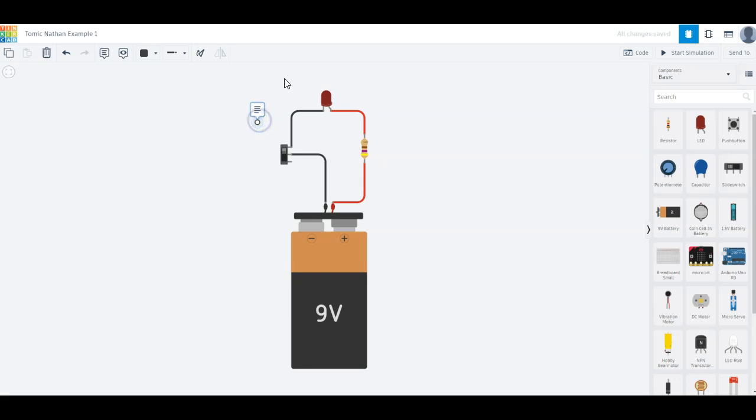All right, so you can put notes for yourself to either explain something or remind you to do something later on. And then one next to it, if maybe these notes are getting in your way a little bit, you can always click on this as well, or use the shortcut key of Shift N, and it will hide your notes. And obviously you can see that that icon changed. It's got a line through it to say, hey, we've hidden any notes there are. So if you're not sure if there are notes, unhide them, and there you go, you can see your note.